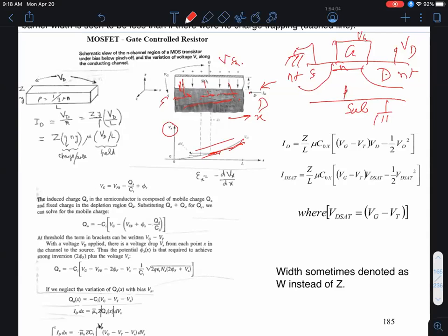So the slope or the electric field will self-adjust to make sure that the product of the electric field and the available carrier concentration gives you the same current at any cross section. Now, to analyze this, we'll first start off with a simpler device, which is a simple ohmic resistor shown on the left, okay? And I'll write the current-voltage characteristics in a funny way so that you can then make the correspondence to the MOSFET, okay?